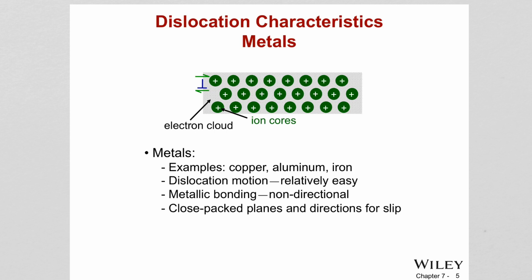Therefore, you need to increase the stress more and more to keep pushing the dislocation over that obstacle. So the idea of strengthening is, as we introduce more obstacles to the motion of dislocations, I have to increase the stresses applied to the material to make these dislocations get over those obstacles. This way I am strengthening the material.